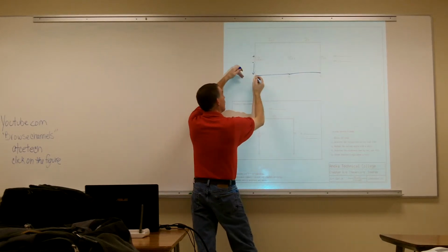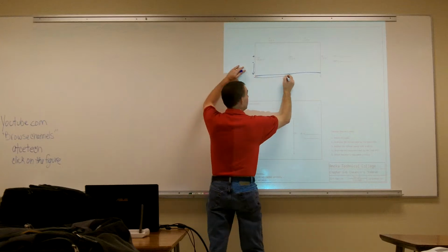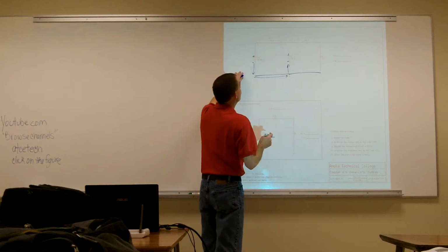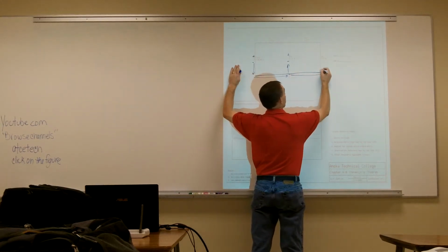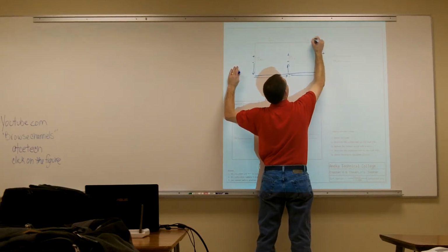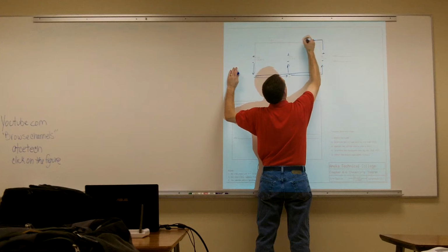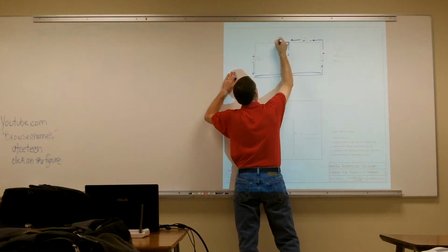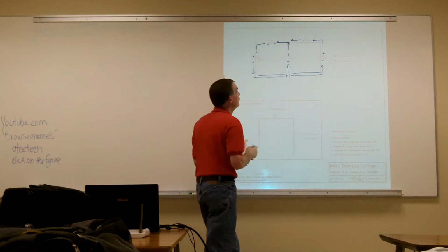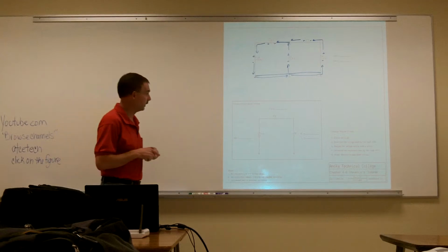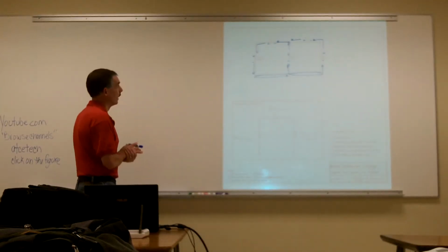Okay, so I've got all my current coming out of my power supply. It's going to come into the first current node. I've got some current going in through R2, and the remainder of my current going up into my load. Then that's going to come in through R3, and combine with R2. Then my total current is going through R1 and back into my source. So I always recommend that you start by drawing your current paths and polarities to find out what's going on with your circuit.